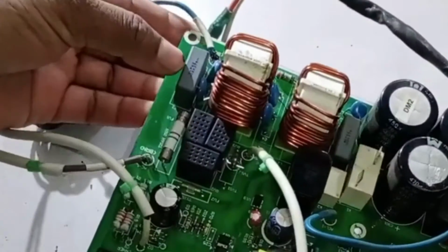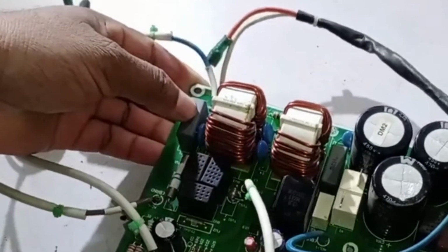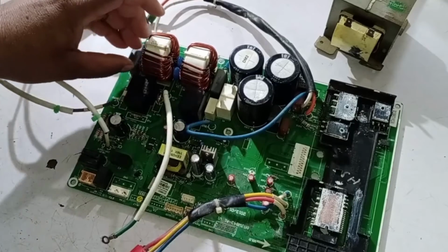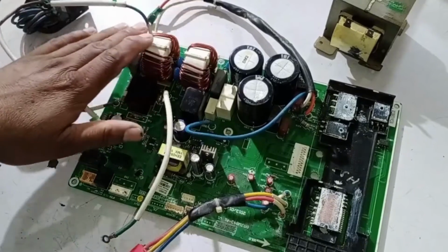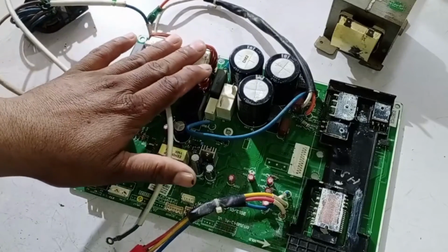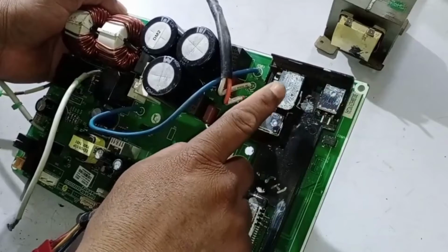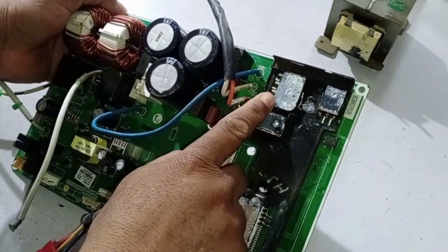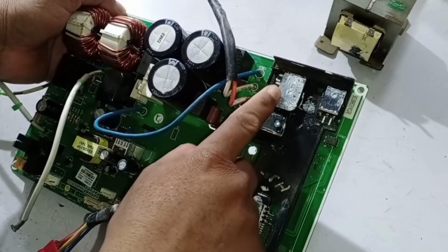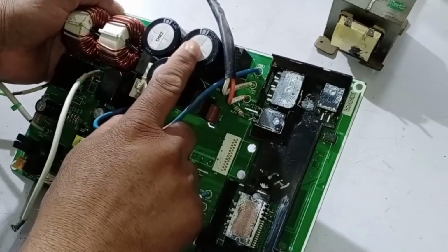If the resistance exceeds this range, it indicates that the line filter's resistance has started to increase, which could mean it's faulty. Before these line filters, there is a small capacitor installed. If there's any fluctuation or issue with this capacitor, it can also cause problems. So you should remove this capacitor from the circuit board and check it as well. When electricity passes through this line filter, it helps filter and purify the AC electricity. After that, the system passes this electricity to the rectification circuit. The rectifier also needs to be checked because if there's any fluctuation, voltage spikes, or any damage, it can cause problems. The rectifier's job is to convert AC voltages into DC voltages.